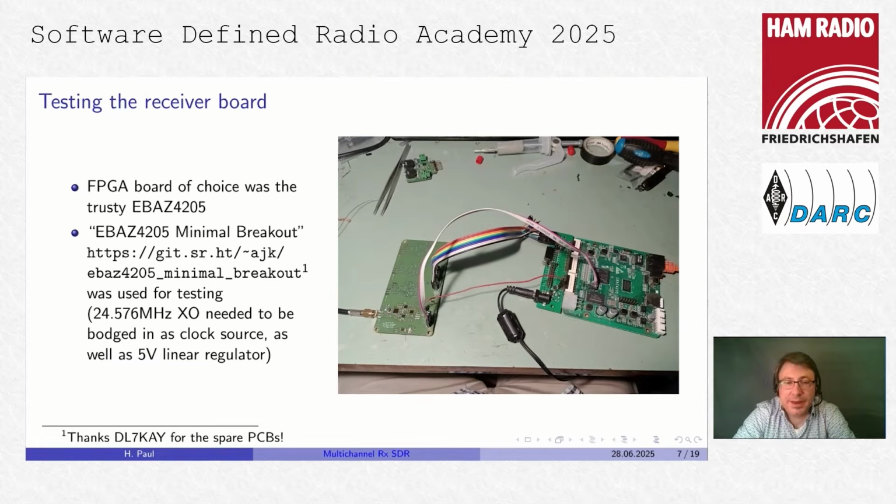And in the meantime, since 2022, others have also realized that this is a very nice board for experimenting. And there now exists a breakout board called the EBAZ4205 minimal breakout. The link, you can see it on the screen. And this is a very useful breakout board that allows powering the board with 12 volts and offers access to all the I/O pins using PMOD headers and standard 100 mil pin headers.